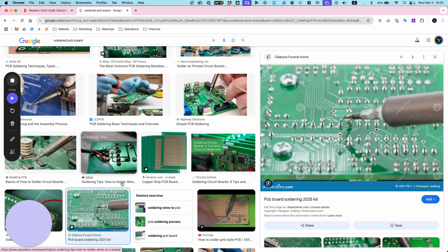You're going to have to know, I'm using a 4S battery. Therefore, my range is what you see here on the screen. It's between 12.8 and 16.8. And whatever voltage you get is your in-between, is like your percentage. You kind of have to do that math. Every battery is going to be different. If you're going to do a 3S battery, what would that voltage be between 0 and 100?